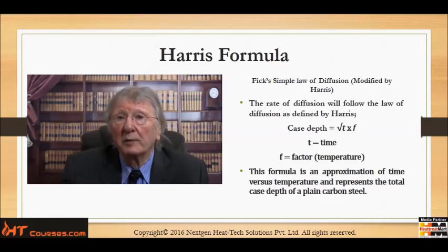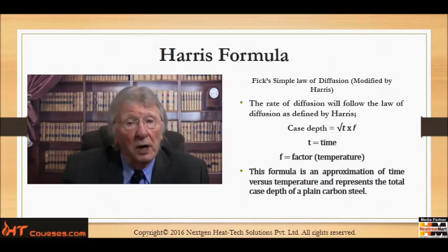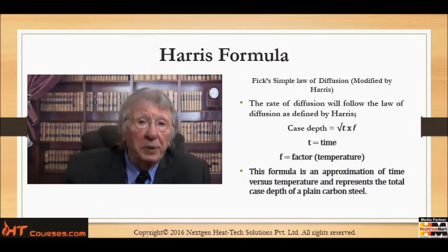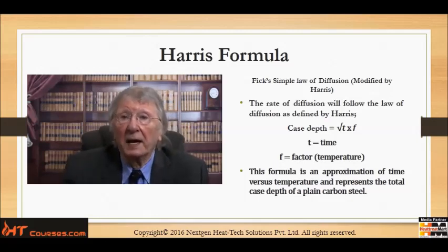And he came up with a very simple formulation based upon a plain carbon steel, not an alloy steel, but a plain carbon steel. And it is simply the case depth equals the square root of time multiplied by a factor. T equals time and F equals the factor, which is temperature derived.